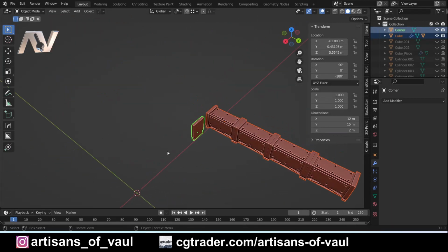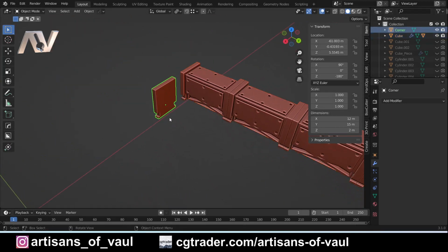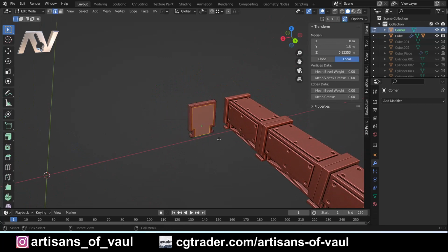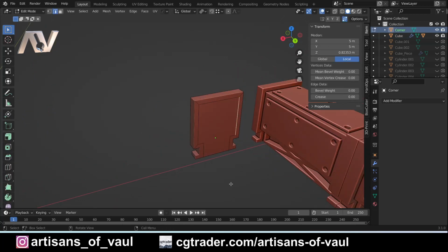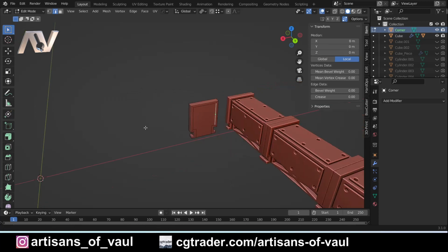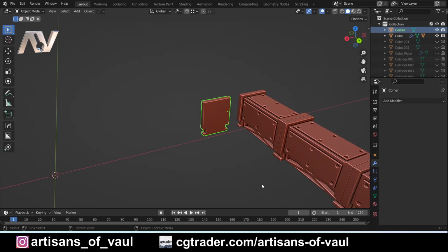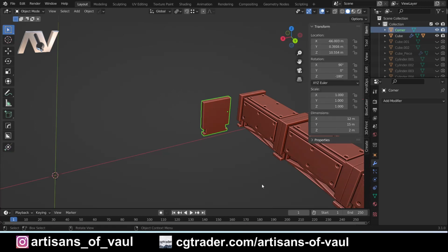Now the first thing we need to do is make sure that the origin of the object that we're going to rotate is going to be on that edge. So I'm just going to go to edge mode, select that edge, Shift and S, and I'm going to move the origin to the edge that's been selected. So just there. Now at this point, if I go back into object mode and I've got my item information out using the N key, mine's already out, but if yours isn't, just press the N key and it'll be shown. We've got here its location.